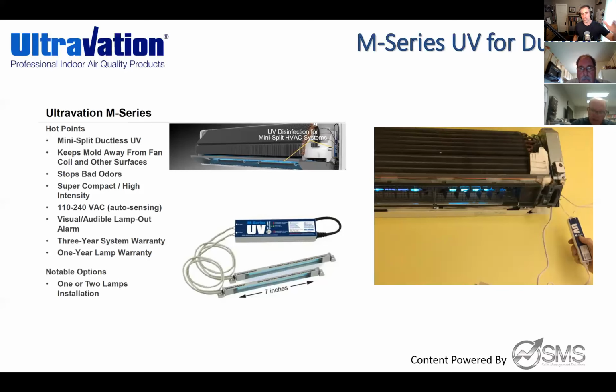Long story short, these things are Petri dishes on the wall. You have to have a service contract on these. You have to be cleaning these, especially environments that have things like yeast, beer, pizza shops, restaurants. I've seen some pretty ugly situations where if somebody hasn't cleaned these things in 3 years, the blower wheel is getting choked up, they can barely move. You take the cover off, you got black spores up inside these things. This isn't fear mongering. This is the truth.